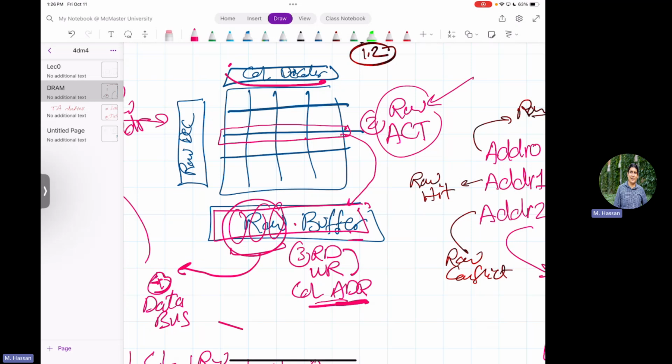Because once you finish the row activation, I can go to the third stage. But if you don't wait enough time, say I did the row activation and immediately after did my reading or writing, what do you expect to read or write? Garbage, because your data didn't yet arrive safely at the sense amplifiers, right? So every single operation is a physical operation that takes physical time.